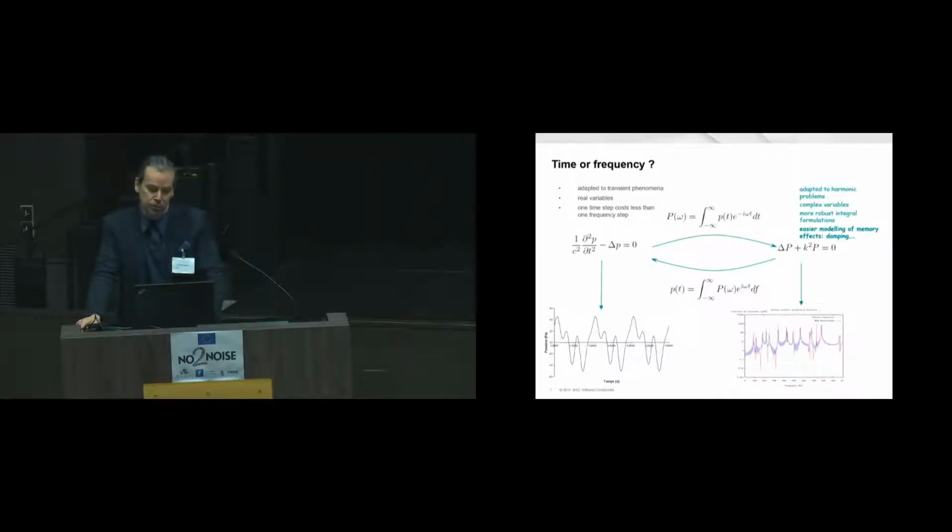Basically, it's just frequency-dependent complex properties. In the time domain, it's much more complex. Usually, you have to retain some kind of history for each of your material particles to be able to solve that. And it can be costly, it can induce issues in stability and so on. So it really depends how complex your materials are. But if they have a memory and complex damping, usually it's much more easy to go to the frequency domain.